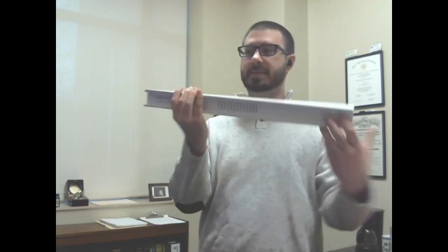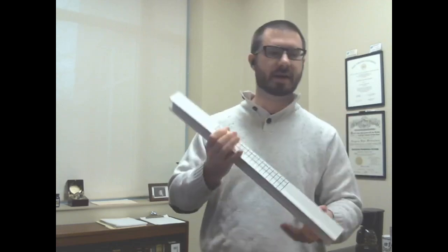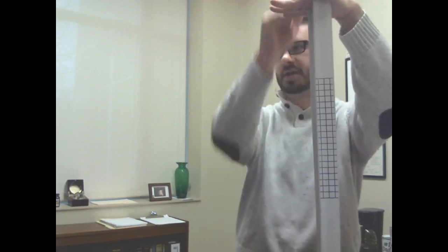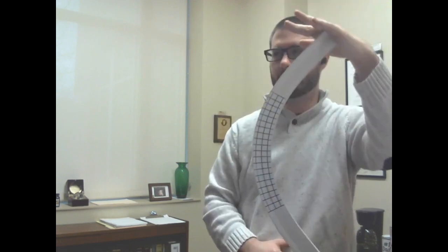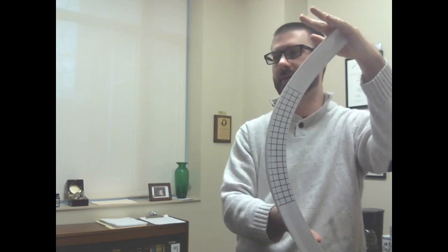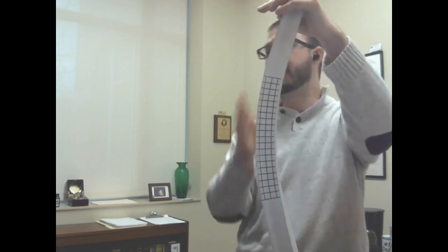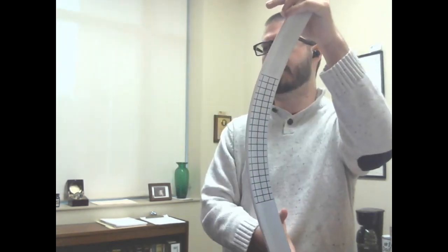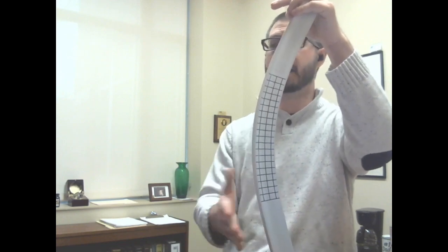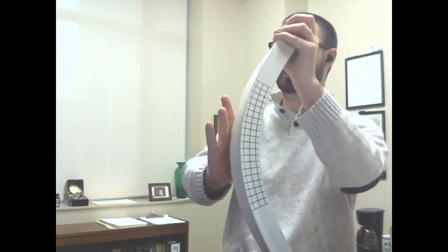So let's say I have a column, and the limits that we're talking about are related to elements in compression. So we're talking about columns and then beams, because if you bend a beam, the top of it, for instance, is in compression. Now, if I take this column and I load it in compression and I push on it, it will accept load until it buckles. Okay. Now, if we talk about buckling, this particular mode of buckling has a name. We call it global buckling. So the whole column kicks out.